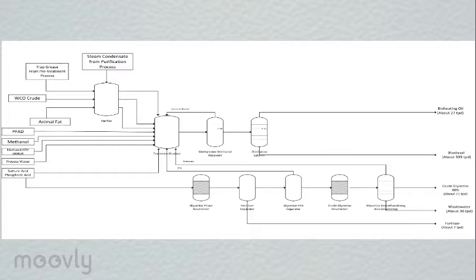Next, the glycerin phase neutralizer process is used. In this process, glycerin from transesterification and the aqueous phase of the methyl ester purification are processed together in the acidification vessel. Potassium hydroxide and the potassium soaps are transformed with sulfuric acid to potassium sulfate, glycerin phase, and fatty acid phase in this process.